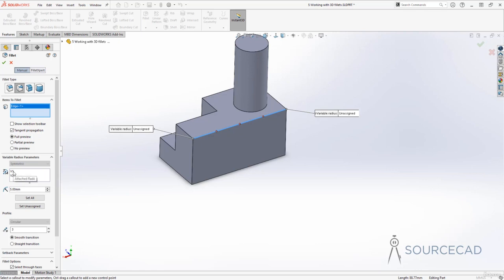Now we have two vertices, V1 and V2. Select it, and actually the V1 is this one. As you can see, when I selected V1, it selected this, then V2 should be this, and yes, it is V2. So you can select these vertices and now change the radius separately. So I'll select V1 and I'll make it, well, maybe 6. Then I'll go to V2 and I'll make it 12. All right, so there it is. So V2 is 12 and V1 is 6.